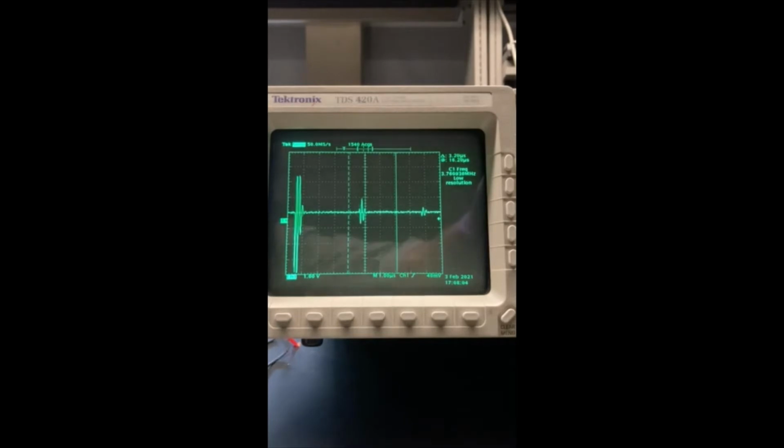It is important to note here that the measurement of the time delay between the pulses becomes a function of how accurately you position the cursors on exactly the same portion of the waveform from one pulse to the next. What we've done here is to pick the same pulse in the sequence in terms of their heights, and use that to determine the equivalent position of the pulse from one pulse to the next.